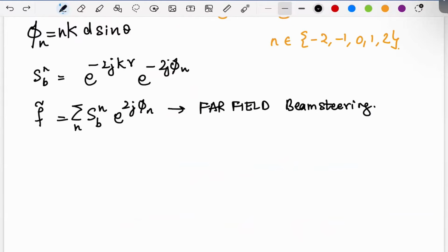So the question that we now have to ask is, since we have TX and RX elements and it's not a synthetic aperture, let's say it's a real aperture, I have these 5 elements that are physical. Of course, in synthetic aperture, you can't transmit from one location and look somewhere else, because you're transmitting and receiving at a single time. But if I have a real aperture like that with 5 elements, each of which has TX and RX capability, then can we use the cross coupling terms?